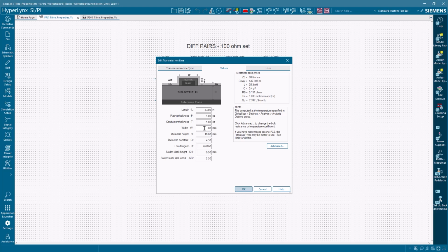Modify the width of our microstrip now to 3 mils. Based on our previous findings, what change would you anticipate for Z0? Well, as anticipated, the Z0 value increased. Making the signal trace narrower elevates the characteristic impedance. This outcome aligns perfectly with our parallel plate capacitor analogy. Reduced capacitance inherently leads to higher impedance. We'll now revert the width to 5 mils for our final experiment.